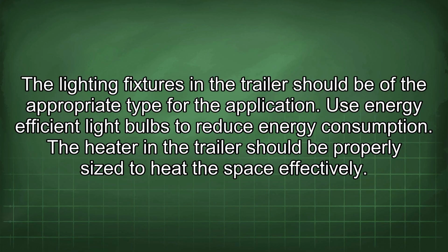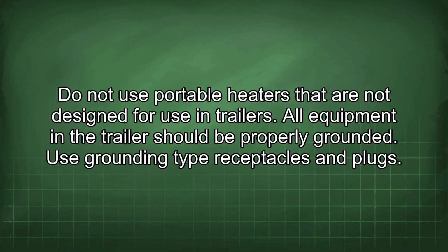The lighting fixtures in the trailer should be of the appropriate type for the application. Use energy-efficient light bulbs to reduce energy consumption. The heater in the trailer should be properly sized to heat the space effectively. Do not use portable heaters that are not designed for use in trailers. All equipment in the trailer should be properly grounded. Use grounding type receptacles and plugs.